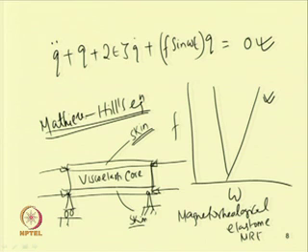So, in today's class we will develop the equation of motion of a parametrically excited sandwich beam with soft core. The core may be soft or it may be stiff. When it is stiff, then the displacement of top and bottom layer will be the same, and one can use the classical sandwich beam theory, and if the core is considered to be soft, then one can take higher order theory to derive the equation of motion.